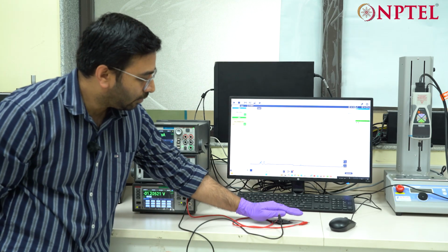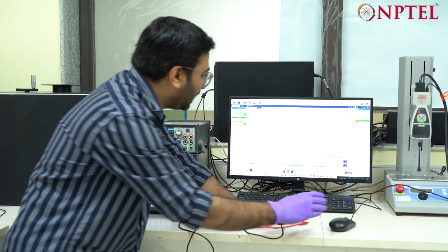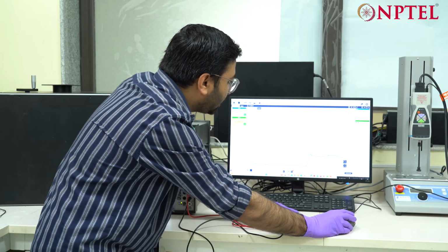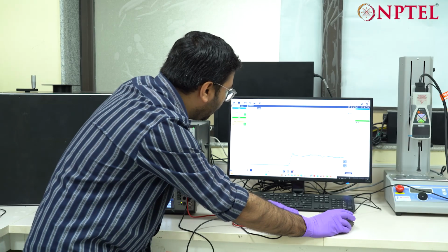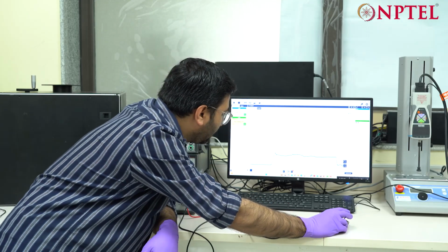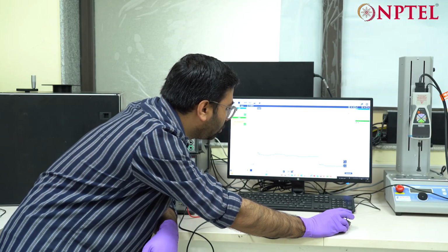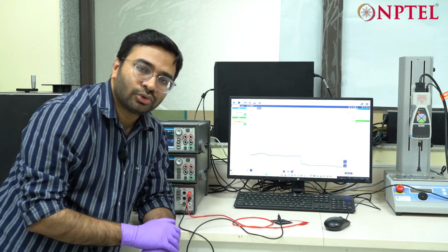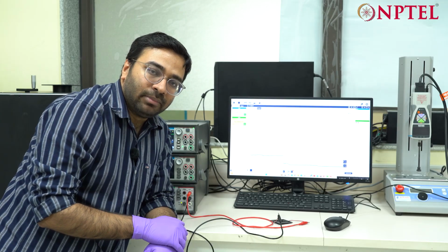Again, if you make a shadow on top of this solar cell, you can see that the value has now basically decreased. Visually you may see that it has increased, but it's a negative potential, it's minus. So magnitude wise it's basically less, it's now minus 1.1, and without shadow it is basically minus 2.2. So this experiment also shows that a solar cell can be used as a sensor if needed,